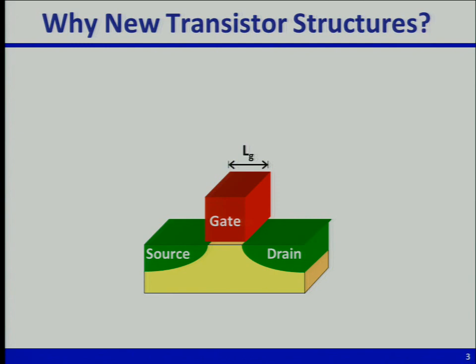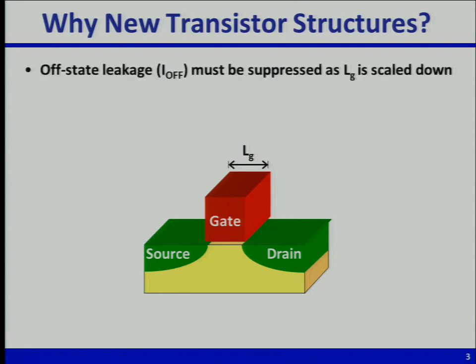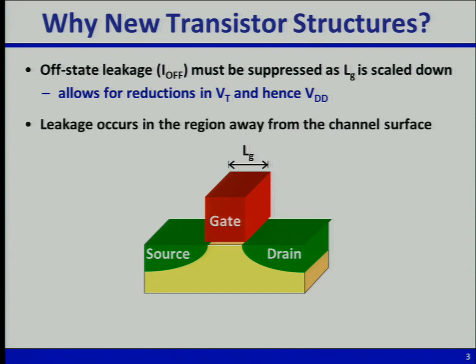Now, in those days, people had tried to make the conventional MOSFETs with such short gate lengths, but then the leakage current was really high, right? Short channel effect was bad. Drain-induced barrier lowering was bad. So a lot of challenges, okay? So the primary challenge at that time, in the late 1990s, was getting the transistor to turn off properly, because the gate was no longer able to turn off the transistor with a high drain to source voltage, okay?